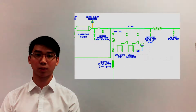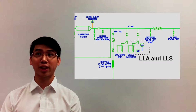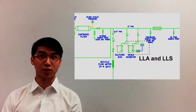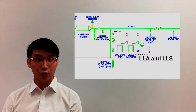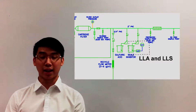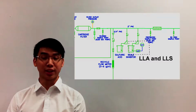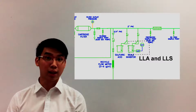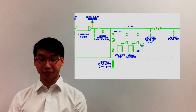If a chemical reaction does happen, it will form scale on the RO membrane, which will affect the RO membrane performance. Careful observation of the P&ID diagram shows that the anti-scalant pump is installed with a low-level alarm (LLA) and a low-level switch, which is LLS. In the event that the anti-scalant flow from the pump is below the optimum level, the LLA will sound and the LLS will switch off the pilot system.